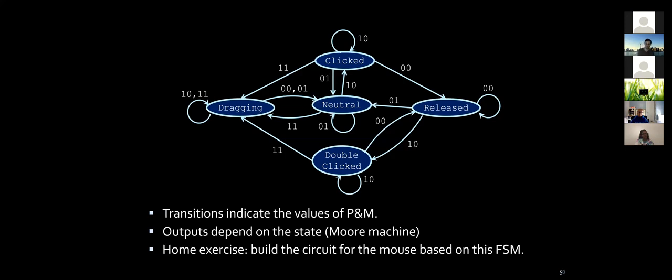And for that state table, you're already aware of the problem of asynchrony, so you're going to try to assign things in the truth table, in the state table, such that we avoid multiple bit flipping at the same time if possible. And then we'll try to get the final circuit and just test it, to see whether it works or not. You can use Logisim or something like that.